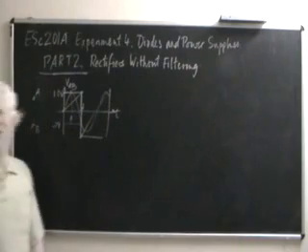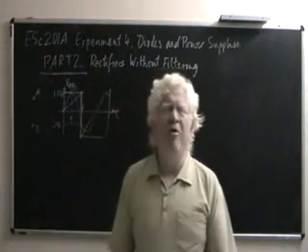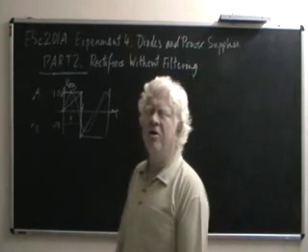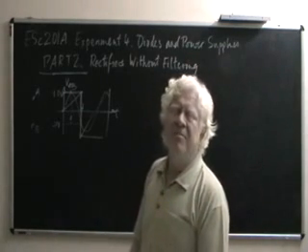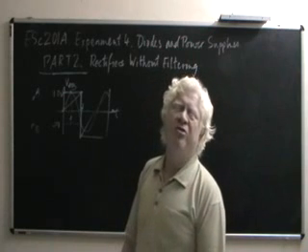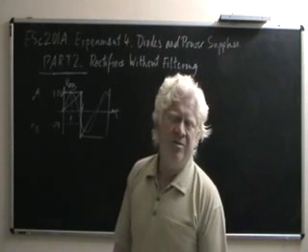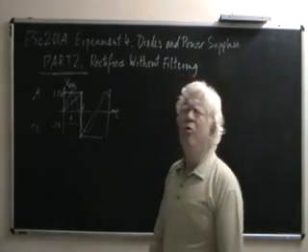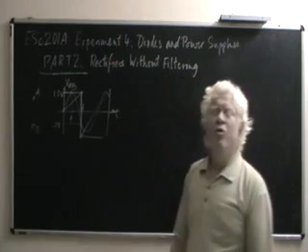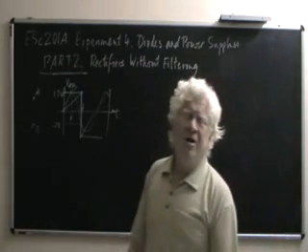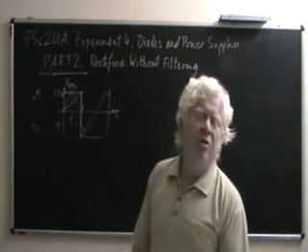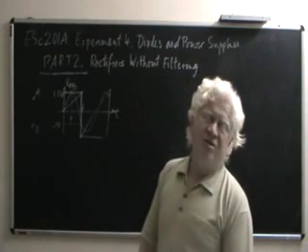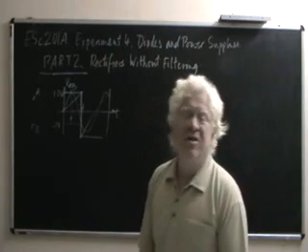So it is not a question of what shape the waveform is, what shape the function of time is. When we say that we have an alternating voltage, we simply mean that the polarity can be both positive and negative at different times. So what we want to do with a rectifier is to convert this alternating voltage into a unidirectional voltage. Ideally a constant unidirectional voltage, but at least a unidirectional voltage.